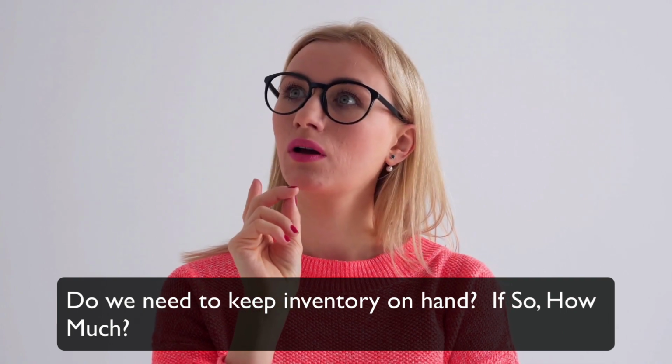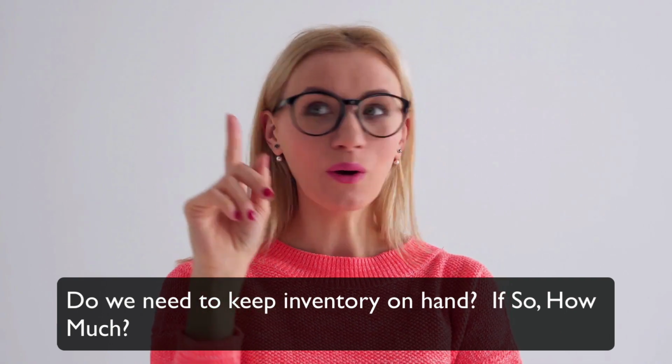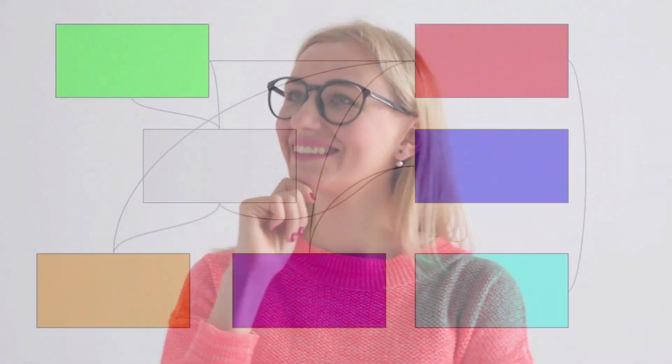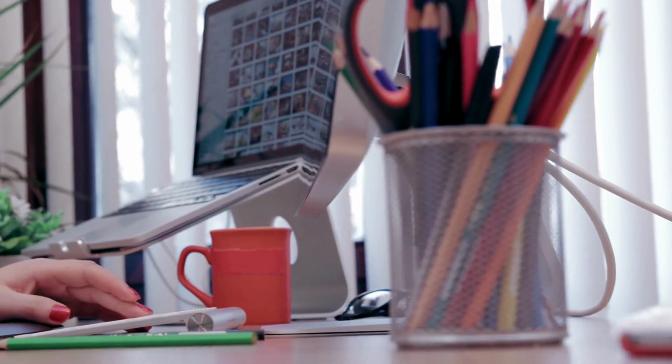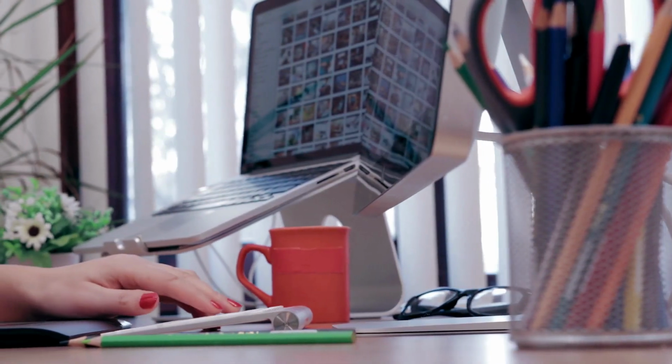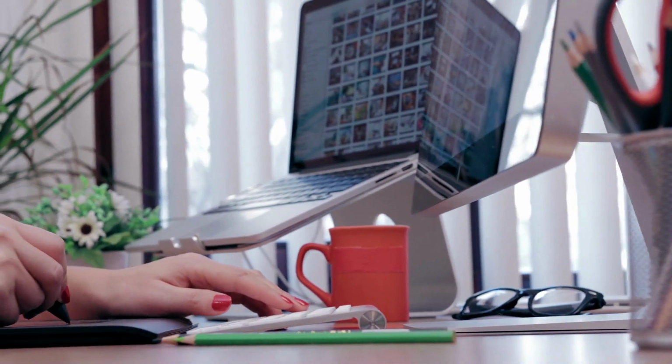If so, how much? As you consider these questions, you may also wish to map the flow of items with a spaghetti diagram or flowchart, review distances, and ensure that items are at ergonomic levels and with safety in mind. Keep in mind that various improvement tools can be used to reduce or eliminate remaining waste in your external process.